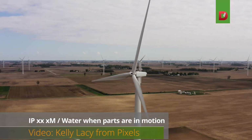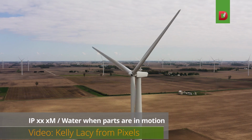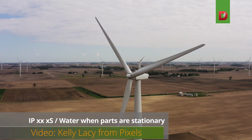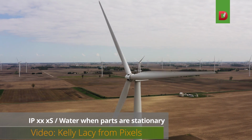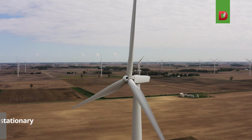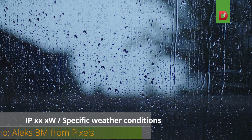Letter M means test effects of water ingress when moving parts of the equipment are in motion, like the rotor of a rotating machine. Letter S means test effects of water ingress when moving parts of the equipment are stationary, like the stopped rotor of a rotating machine. Letter W means the device is suitable for use in specific weather conditions, with additional treatments or protection measures.